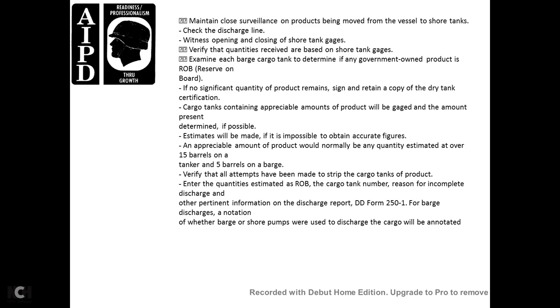Verify all attempts have been made to strip the cargo tank of the product. Ensure the quantities are estimated on the reserve on board for the cargo tank number, the reason for the incomplete discharge, or other information in the discharge report.